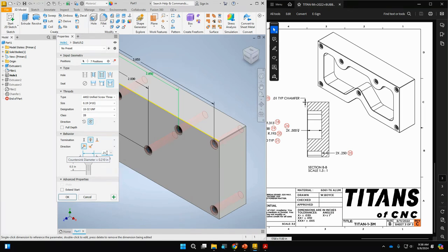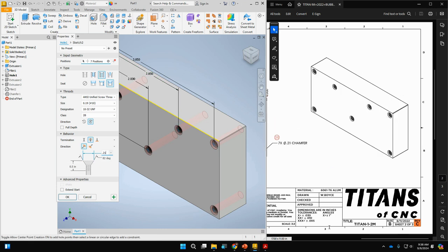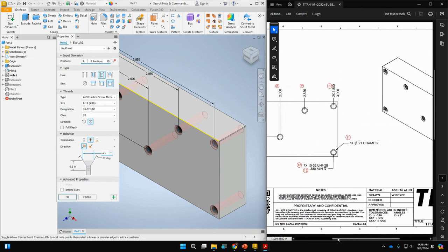All right. And so that's going to give me my countersink diameter. And the angle here of 82 degrees is what we're going to do. This does not tell me that there is a specific angle to it. So we're going to just kind of leave that as it is right now. The chamfering tools that I have are not going to give me the 82 degrees, but we'll just leave it for now because it'll kind of select that chamfer for us later.